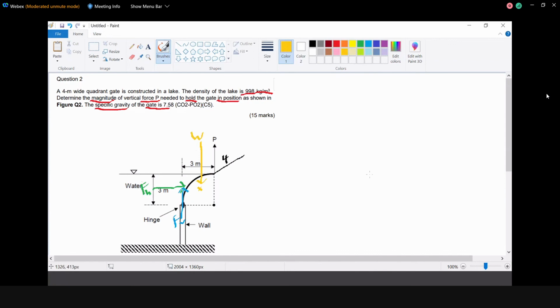Okay, if you can come up with the moment equation, that's even better. If you want to start with the equation for the moment, that's better. But if you want to start with the steps of finding HG, finding the area, finding the volume, finding FV, finding FH, that's fine. So let me first show how the forces produce moments. So you have FH. It's hard to draw here, so I will just paste the picture. Wait a moment.